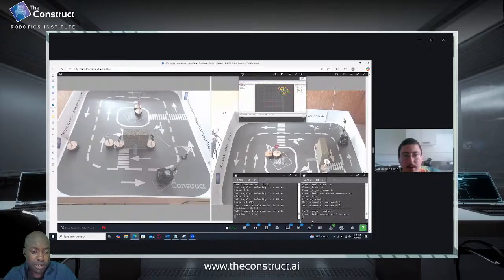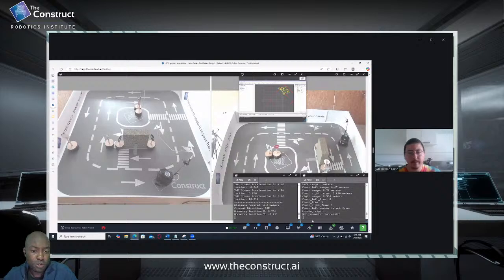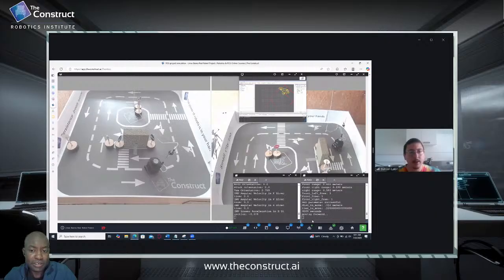Based on the sectors and the threshold distance that we've got, would it fit between those two obstacles? So I assumed that 0.3 meters clear would allow it to move with the space available, and there's a sleep command to make sure it doesn't overshoot and accidentally hit an obstacle.